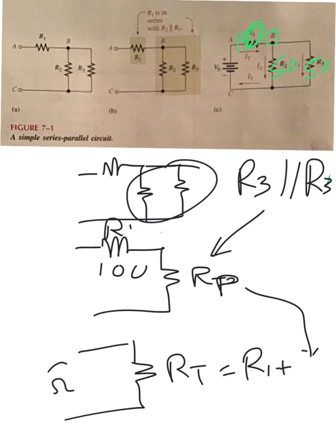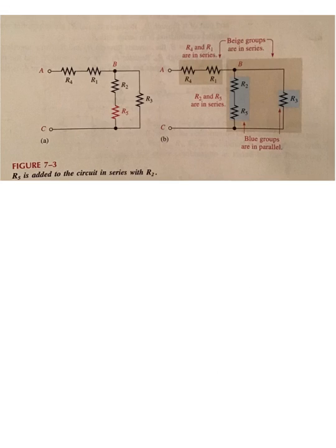In other words, we would put an ohm meter in here, and the ohm meter would measure 150 ohms due to all the resistance in the circuit. The meter is inserted in exactly the same spot as the battery. So to measure resistance, you have to turn voltage off, you have to remove the battery, and you have to insert the ohm meter.